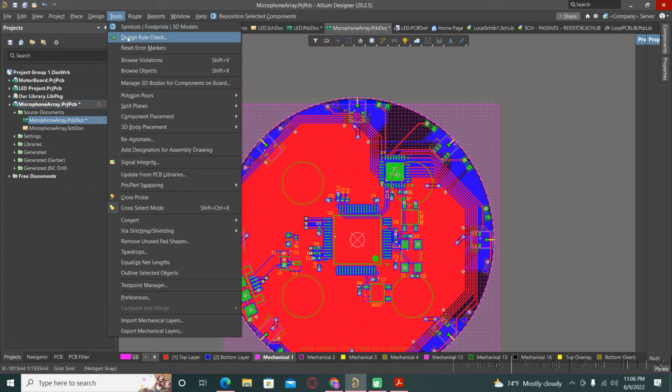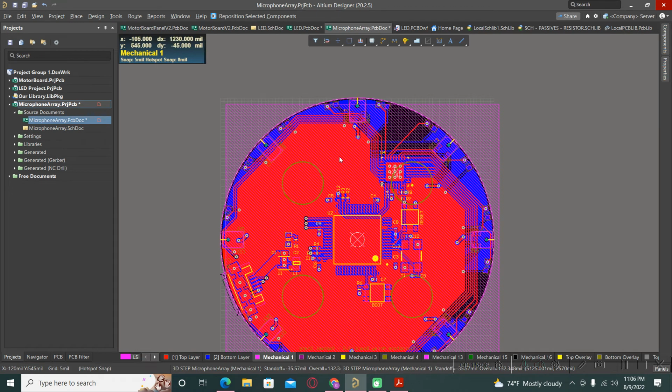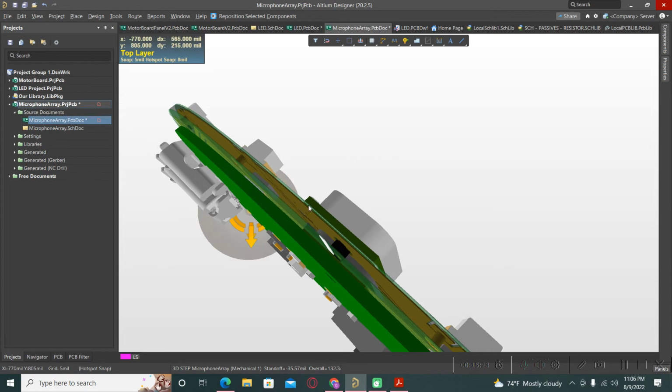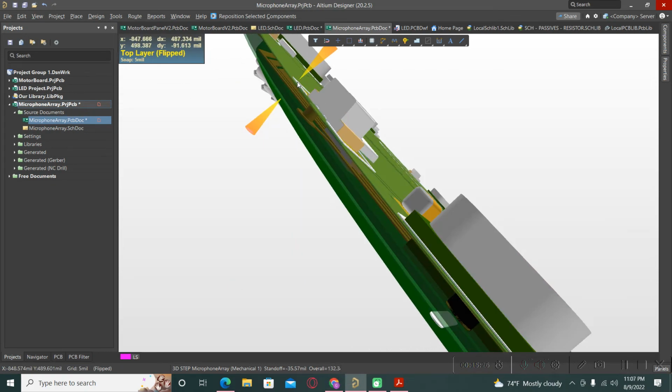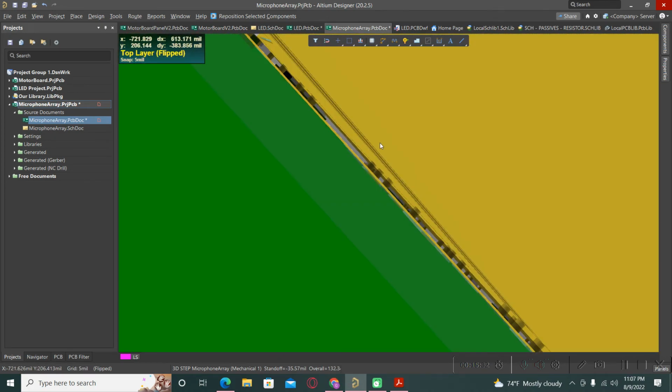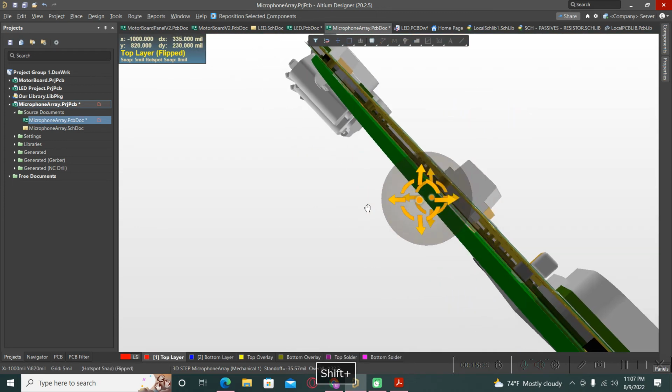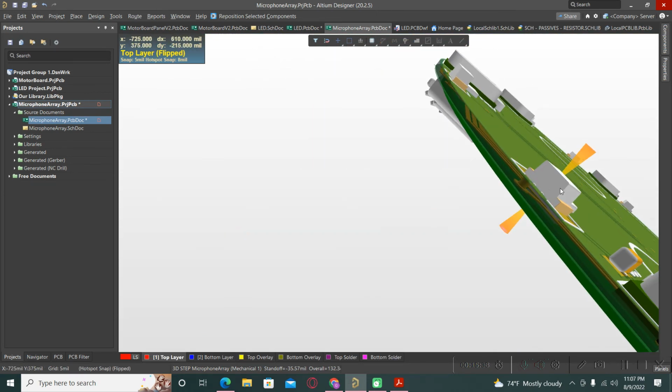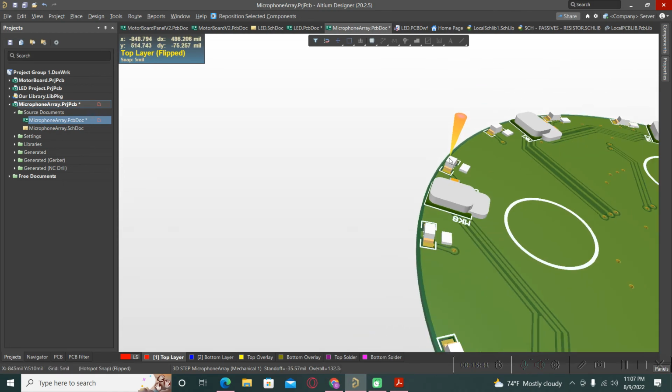When you have some holes and you have two PCBs with the same shape that will be connected together, you can simply put one over the other and check the holes and whether everything is in the correct position and respects the minimum distance, and everything is okay and you don't have any issues relating to collisions or the clearance of the components.